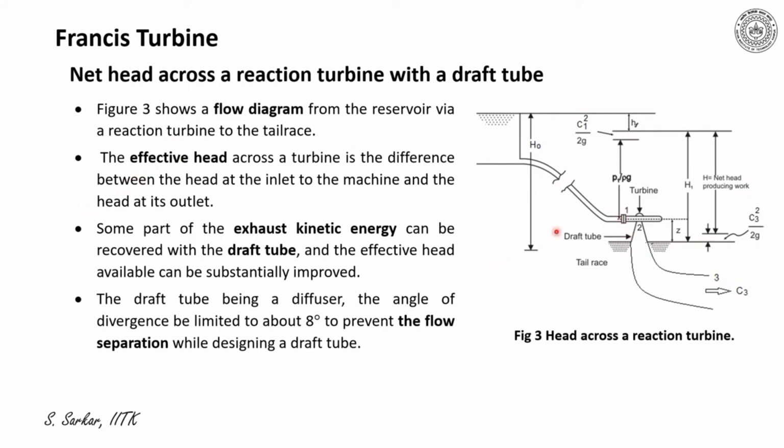However, at the state point 2, what is the kinetic energy of the fluid? That can be treated as a loss. Now, some part of this exhaust kinetic energy can be recovered with the draft tube.